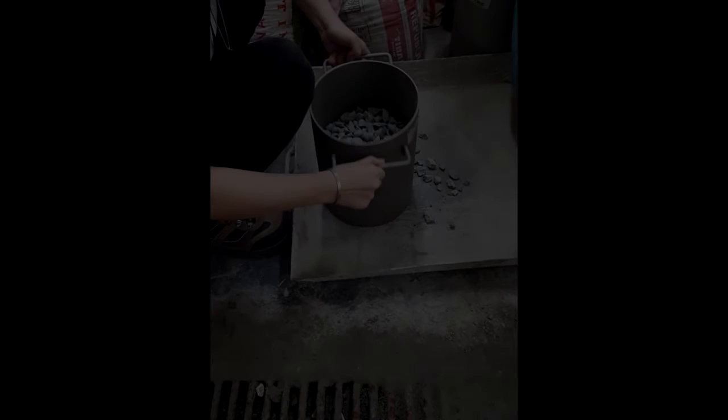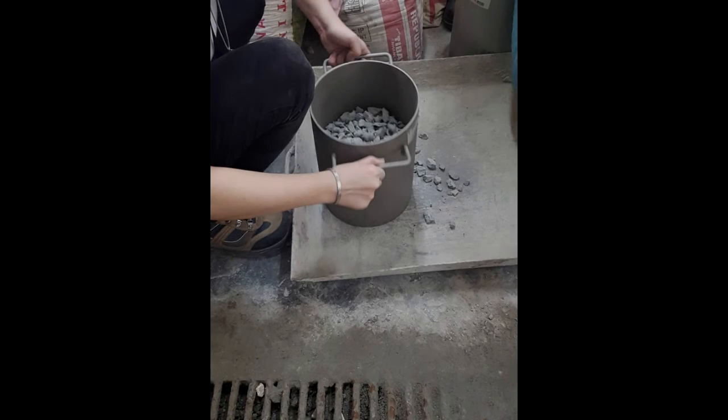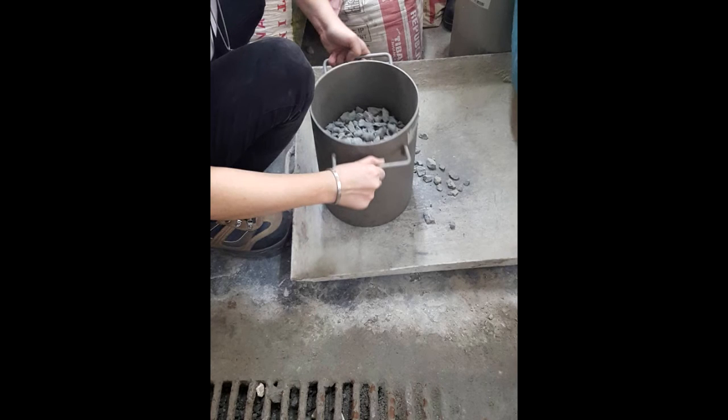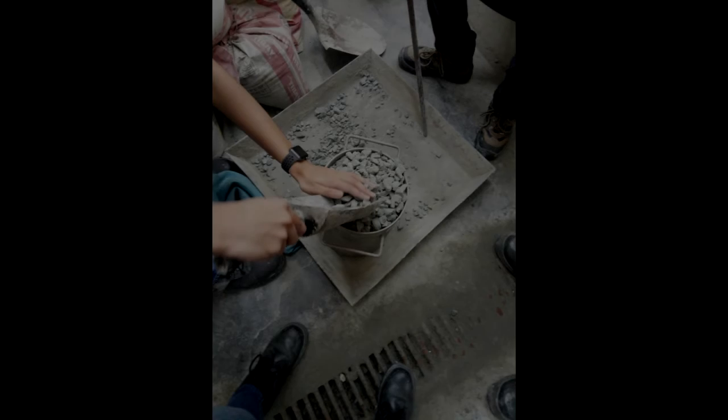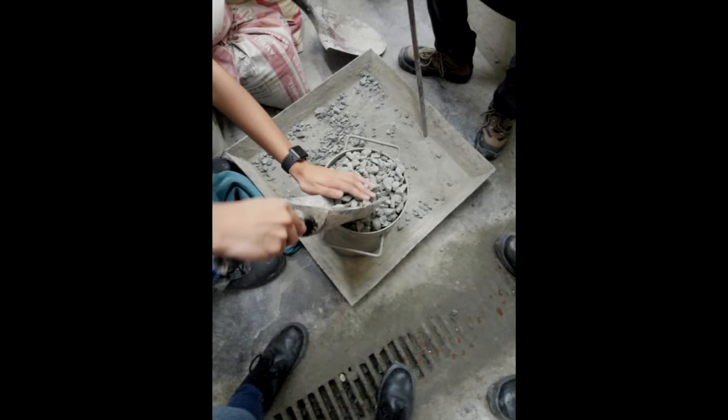For this experiment, we are tasked with finding the unit weight of aggregates. This is important because knowing the unit weight of aggregates would give information on the amount of air voids present in your aggregate sample. This is reduced by using different compacting methods like jigging, rodding, and shoveling. If there is a small unit weight measured, it means that less air voids are present, therefore encouraging more contact in between aggregate particles that would result in a better interlocking effect. This improves the overall strength of the produced concrete.